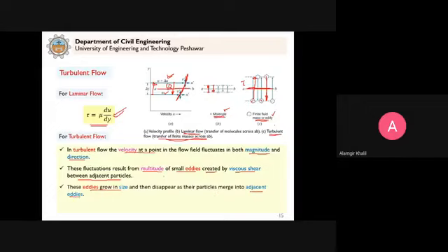So we have a large amount of turbulence. These eddies can merge into one another and grow in size. Thus, there is continuous mixing of particles. This is the important characteristic of turbulent flow. One advantage of turbulence is that we are able to mix the particles of the fluid. If you want to mix any chemical in, for example, water, you have to create turbulence.